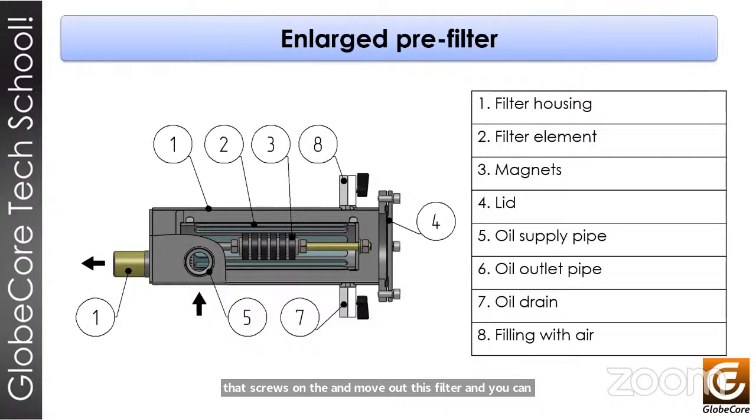You must always try to clean these kinds of filters only with oil, because you don't want to clean with water, because that means you will increase the moisture inside the system. And the good way to preserve these kinds of filters is to clean them with transformer oil.